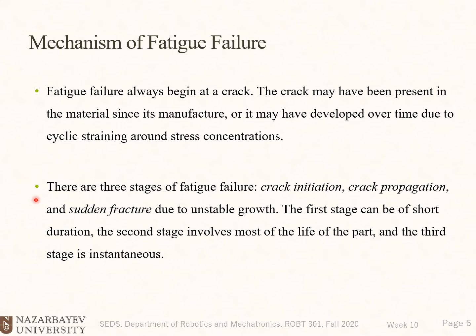and bigger. There are three stages of fatigue failure. Crack initiation, so crack starts; crack propagation, the crack grows; and sudden fracture due to the unstable growth.